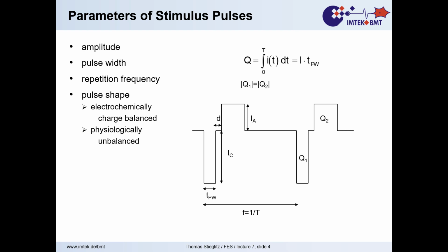So if you look in the latest microelectronics design papers on stimulators, you find that they measure the charge, amplitude times time, but then they also measure, is the voltage really at zero, and if not, should I push more charge in? Can I do this in advance, so that I predict the charge that might be there? Or do I measure it afterwards as a correction measure? So there are many options that you can apply if you take it really seriously at the detail level.